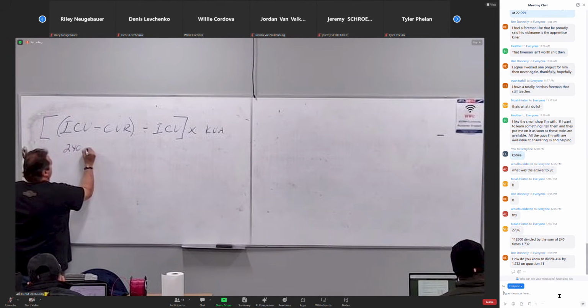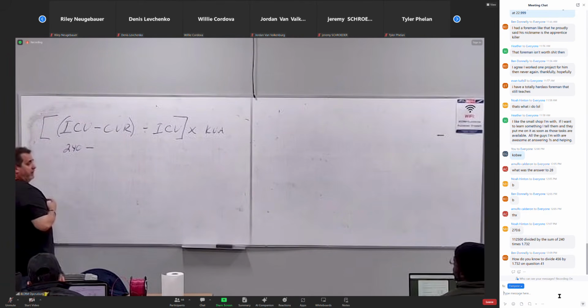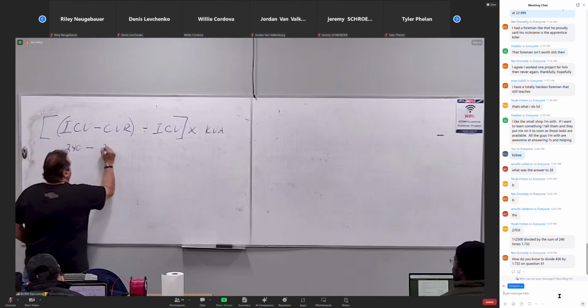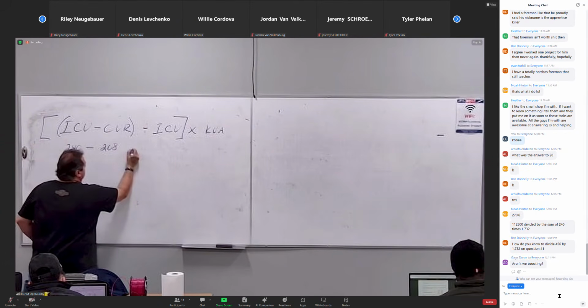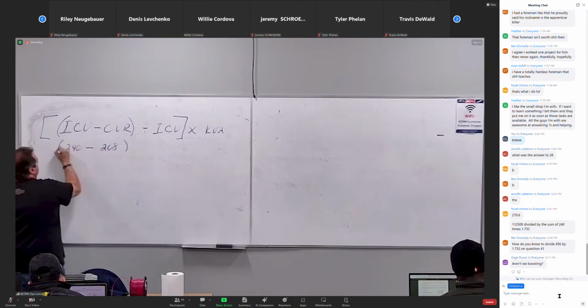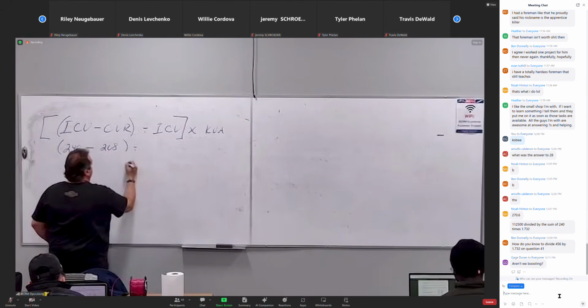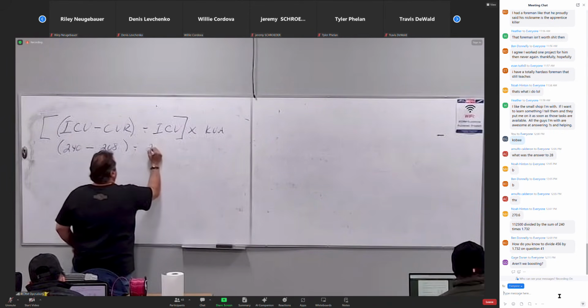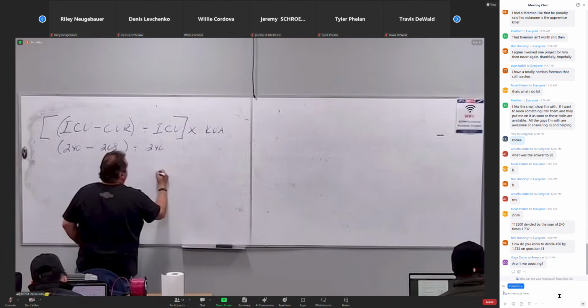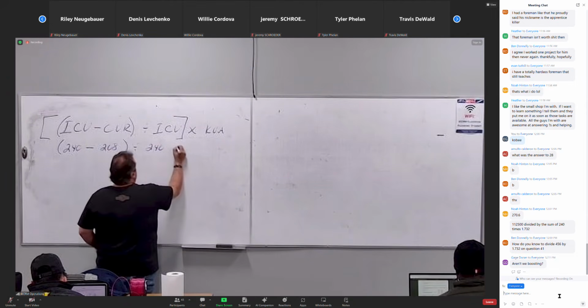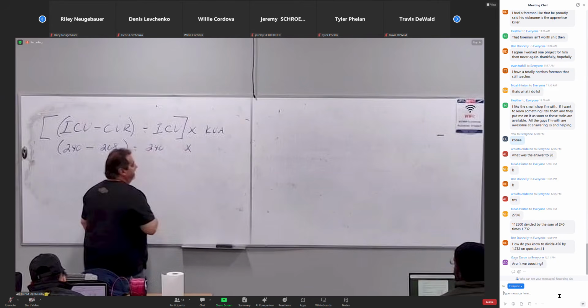Okay, minus, what's the output voltage required? 208. Once we solve that part, we're gonna divide it by the input circuit voltage, 240, correct? Then once that's closed out, we're gonna multiply it by the KVA of the load.